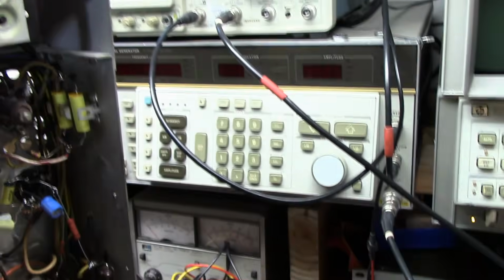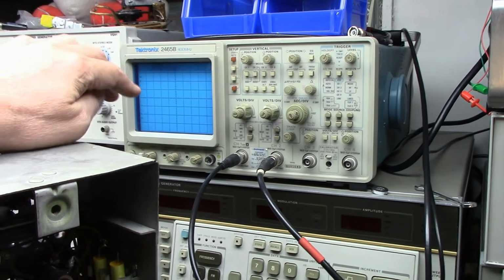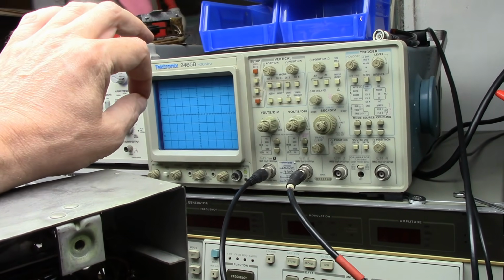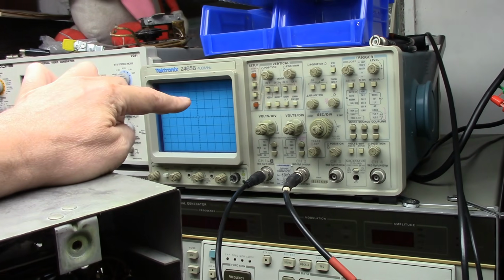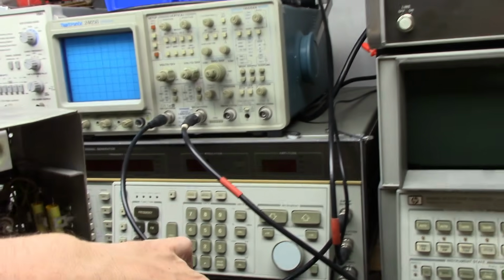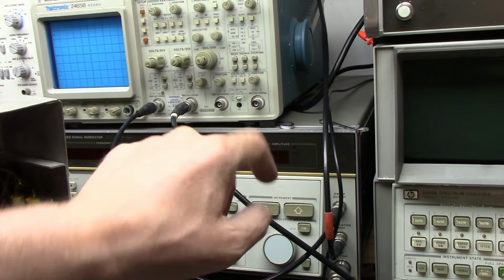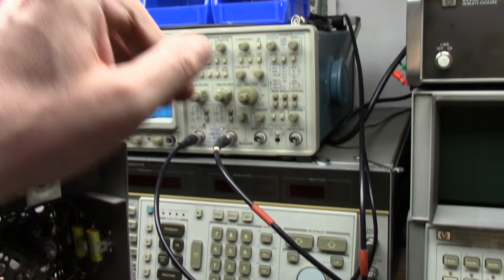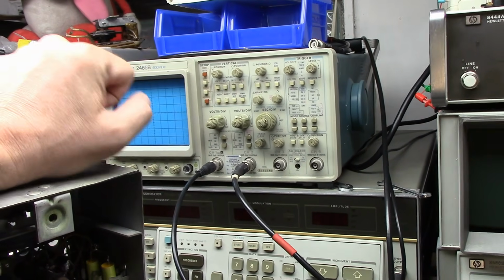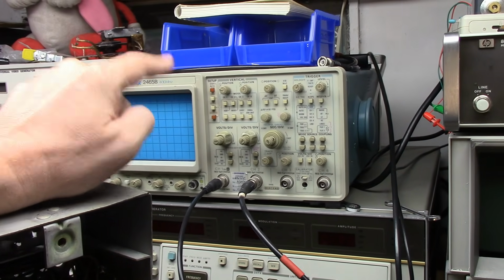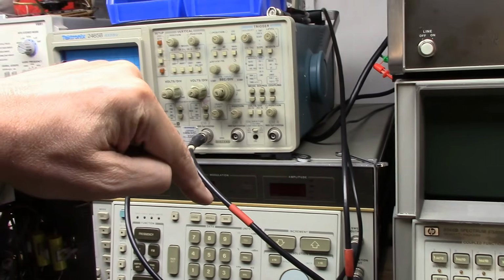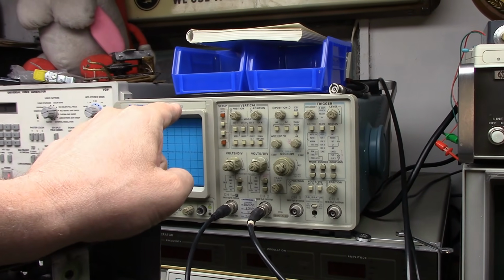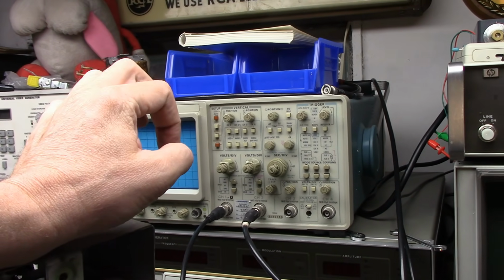Now, I tried doing that a little bit with the scope in XY mode. I wasn't able to see the markers, which should show up as bright dots on the response curve. I thought maybe there was something up with this scope. There is an output on the back of the sweep generator that does put out a pulse at the marker position, and I connected it to the intensity modulation of this scope. However, looking at the specs, the polarity and the voltage levels that this puts out aren't really compatible with this scope. I tried using an older 465 scope, and I could just barely make them out.